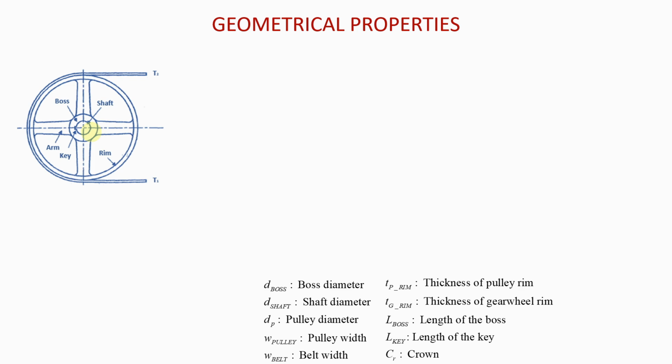And so with that, I can also introduce to you the shaft, because the shaft is designed to fit inside of the boss. The boss has a cut inside for the shaft to fit in. And not only that, you also have a cut for the key. You can see here you have a circular cut in the boss for the shaft, and also you have a small cut that protrudes in this direction, in this case, for the key. I hope you can see what the key is.